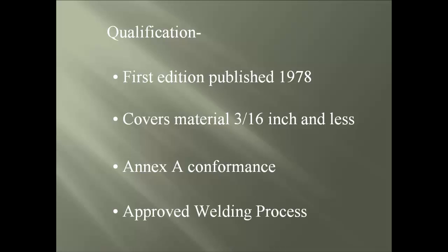The following welding processes are approved, which means there is no test qualification required if used as per the manufacturer recommendation, and they are shielded metal arc welding, gas tungsten arc welding, flux core arc welding, gas metal arc welding, and with this process, all the modes of transfer are allowed. Yes, even short-circuiting transfer mode.